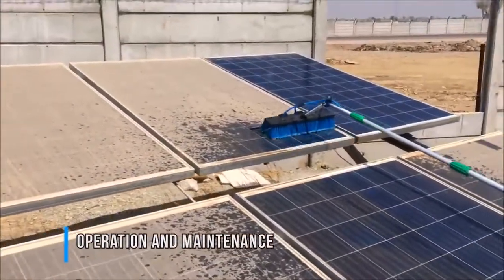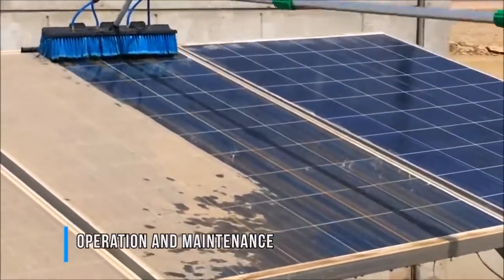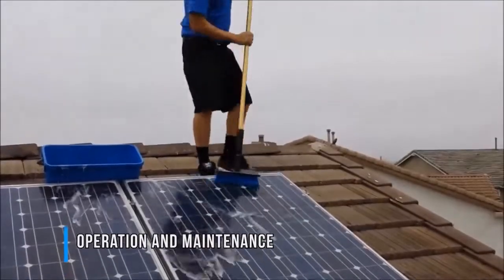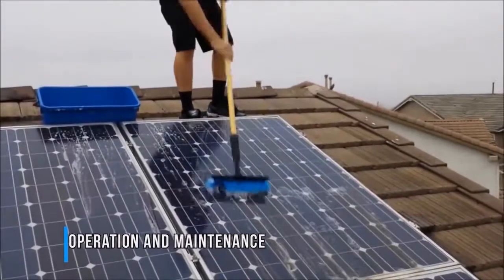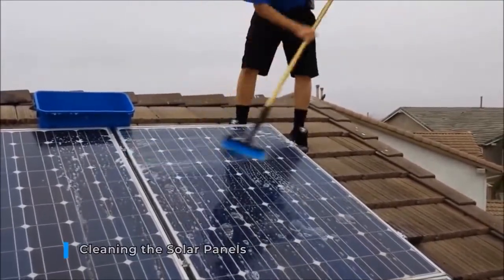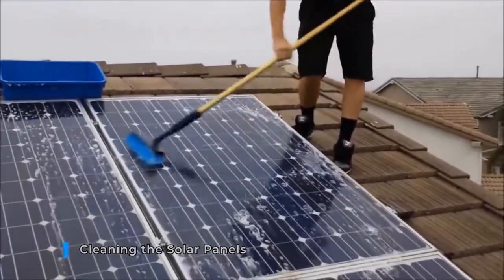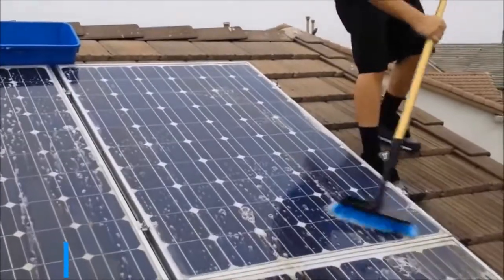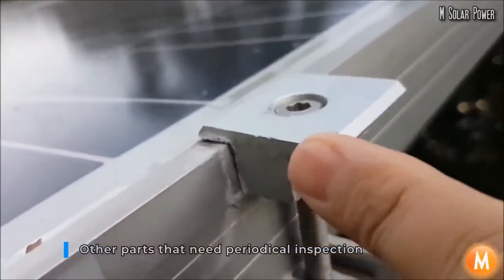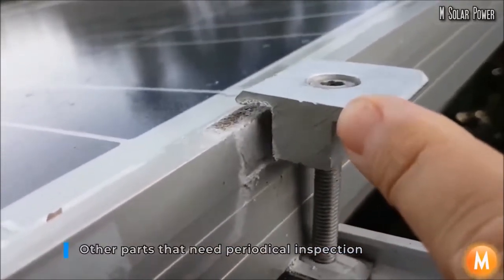As there are practically no moving parts in a solar installation, minimal maintenance is required. However, routine maintenance is needed in order to ensure that the system is performing properly. Solar panels require routine inspection for signs of damage, build-up of dirt or shade encroachment. Although solar panels are usually designed and installed in order to be cleaned by rainfall, they should be cleaned manually if there is a build-up of dust or any other obscuring material.